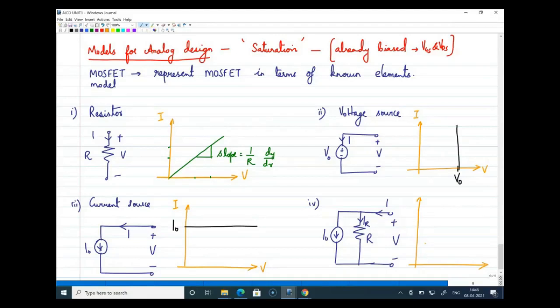All right. What we can do is draw the IV characteristic again. This is V and this is I. When you draw the IV characteristics of this, the current through the current source will remain the same, so it is I naught, right? The current through the resistor will always be linear, so you will see a response something like this. Let me use a different color for that.